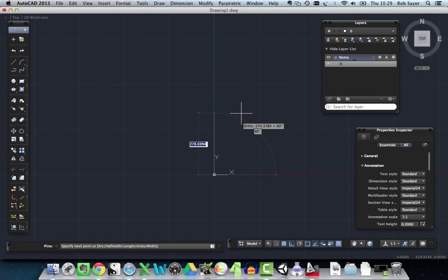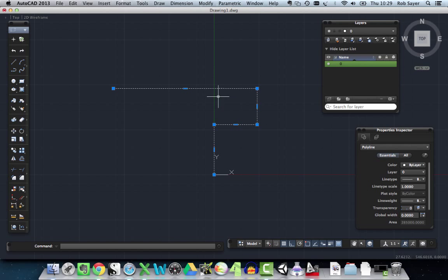Now I'm going to extend it up by 350, enter. Off to the right by 300. Then I'm going to extend my next line up a bit by, say, 250 again, and then all the way back here we're going to go back to 1000. So you see what I've done there is a similar kind of action, only this time I've made a solid object out of it.